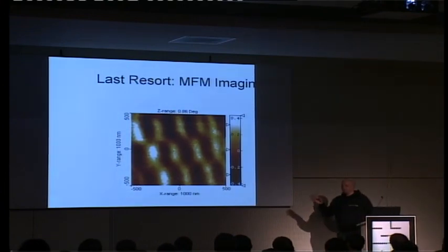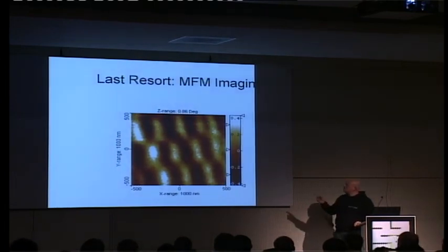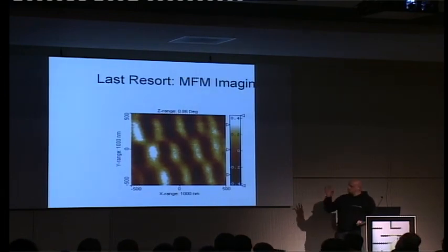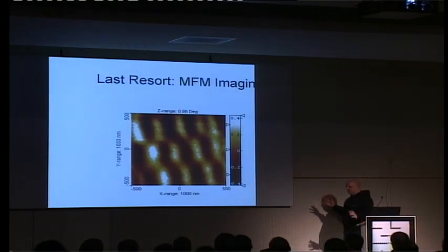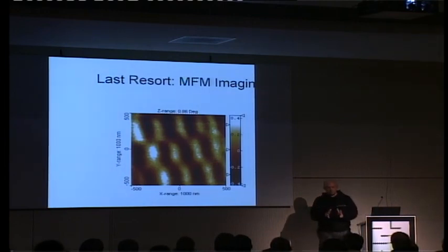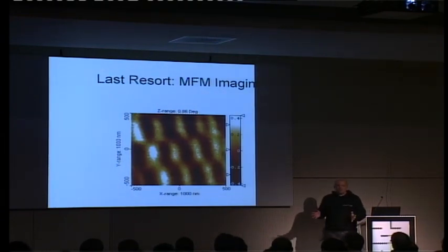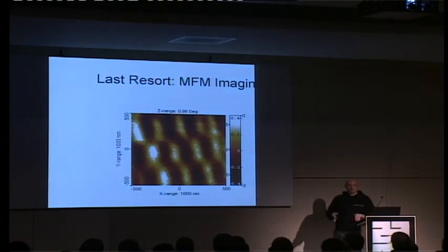One problem with MFM images, well, maybe it's too esoteric, is that what you see on an MFM image is the actual written magnetic transition, and that has nothing to do with the readback signal you get from an MR head, because these transitions are so close together that your MR head gives you back a narrowed signal that goes over 3 or 5 transitions, and you use math to separate them.